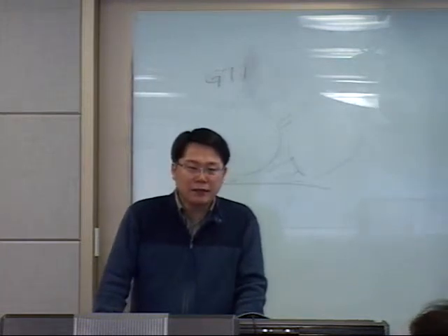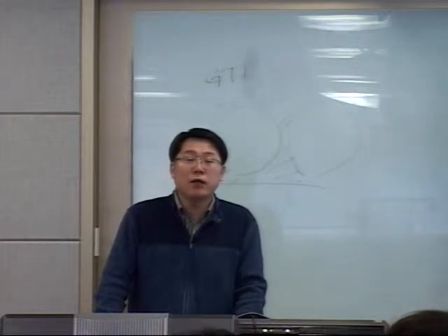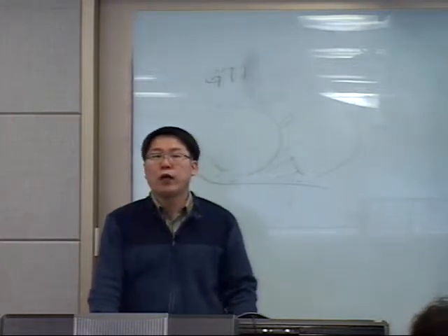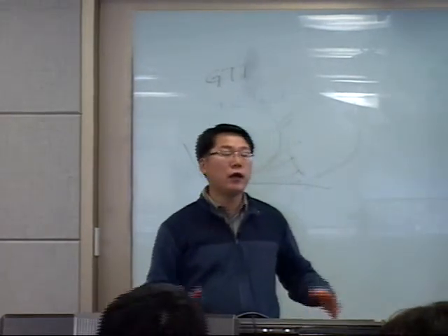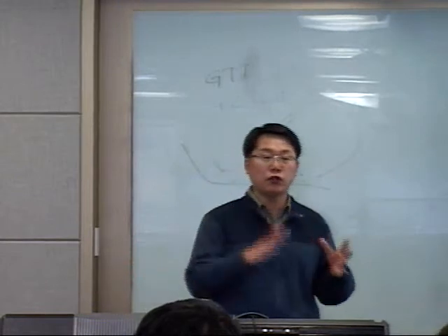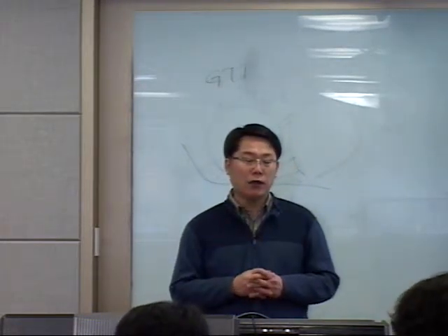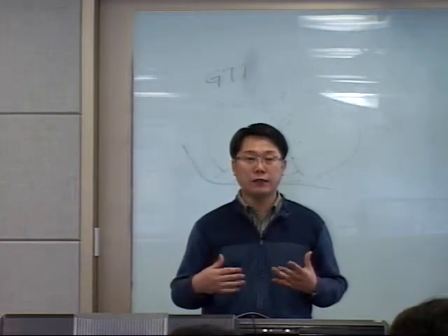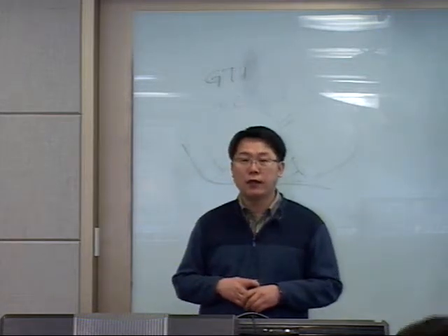Some parts are missing in this slide, but the concept of the reliquefaction system is very simple. We use nitrogen, and if we apply the compression, cooling, expansion concept to the nitrogen cycle, we can get cold nitrogen around minus 70.